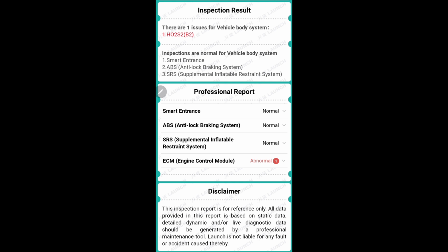Now, this is where my scan tool really shines because it allows me to view the operation of this O2 sensor. And what I show is that the sensor is definitely oscillating, not just that one, but all four of them are oscillating like they're supposed to. As far as I can tell, they are warming up like they're supposed to. It is quite possible that this one might just be old. Again, the truck is a 20-year-old vehicle. And then, you also have to think about the electronics overall on the vehicle as well.